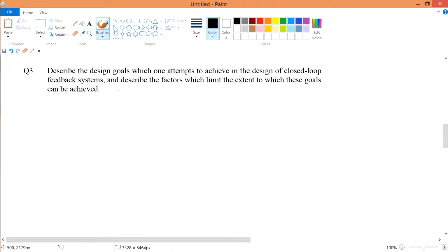When you design a closed loop system, you want your output to be the same as your input. So therefore it's a stable command response, or a good command response. But before having a good command response, you want to also design your closed loop system to be stable. And therefore when you design a closed loop system to be stable, you're going to loop shape.